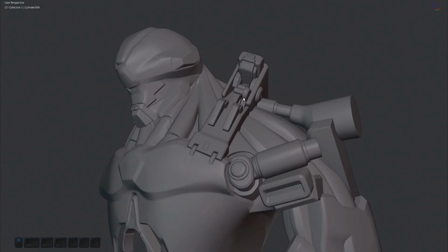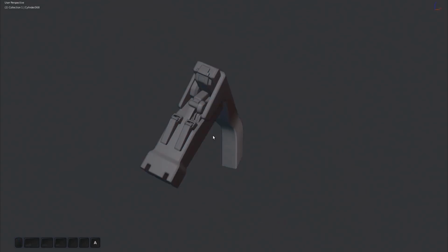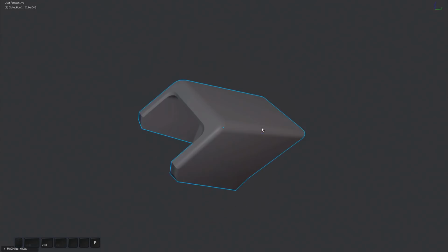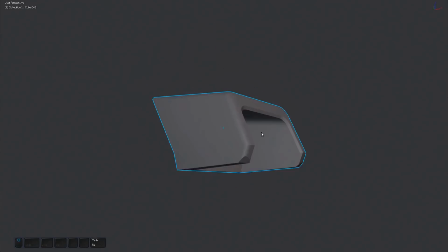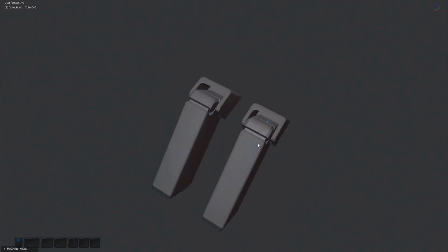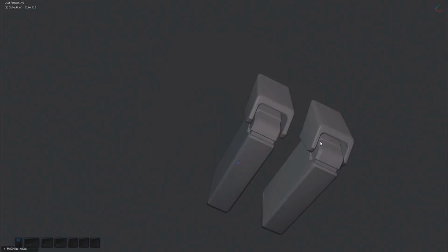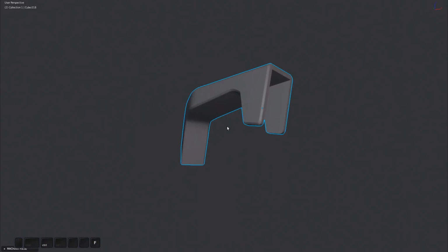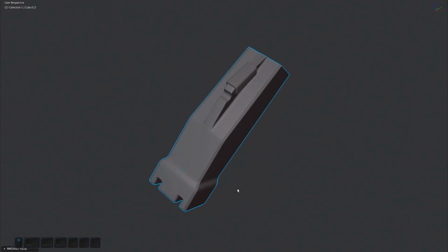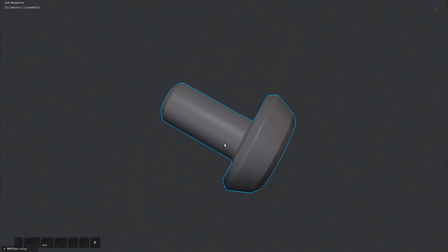What makes this tool special is that it works on multiple levels. You can go deeper with new selections. And deeper again. To go up one level, just run focus again, but with nothing selected this time. It's so easy, and so useful.